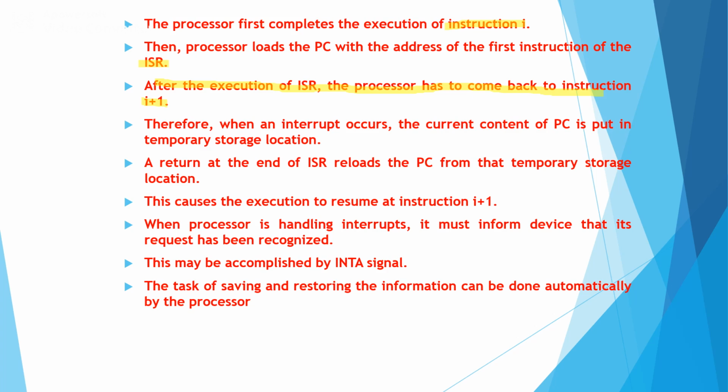When the processor is handling interrupts, it must inform the device that its request has been recognized. So, whenever the interrupt is raised by an IO device, when the processor is handling that interrupt, it must inform the IO device by sending an acknowledgement signal, that is the INTA signal.